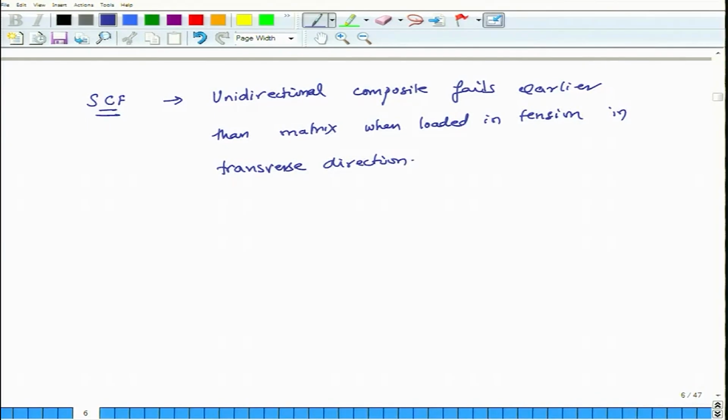So, what will be the failure point of this? So, we can say that its tensile strength in the transverse direction sigma Tu will be equal to the strength of the matrix sigma Mu, and it has to be less than strength of the matrix. So, divided by some factor S. Now, this, or actually you can say it SCF, stress concentration factor. So, if we can know what is this stress concentration factor, we can calculate sigma Tu.